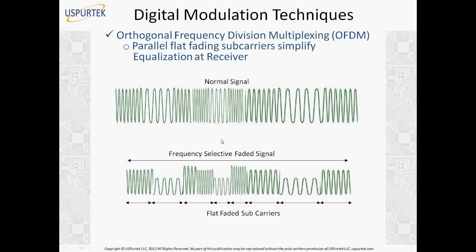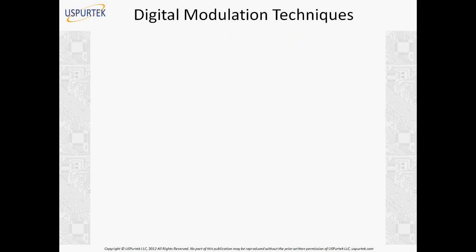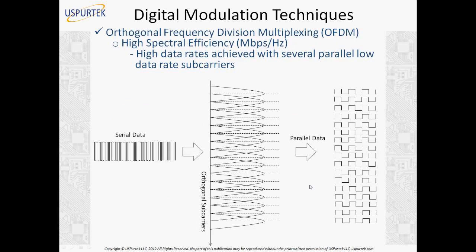So here we have a question. Here we reduce the bit rate, then how can we save increased bandwidth? Okay, let's go back to the previous slide. Here, when we say bandwidth, we mean the bandwidth of the complete OFDM channel, all the subcarriers included. So you add up the bandwidth of each subcarrier, that gives you the total bandwidth. So we increase the total bandwidth, not the bandwidth of one particular subcarrier. So total bandwidth is much more. It may be 20 megahertz, 25 megahertz, or 40 megahertz. But each subcarrier occupies only a very small band because it's carrying a very low data rate.